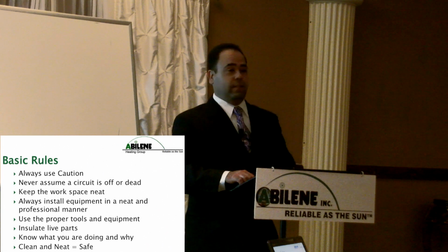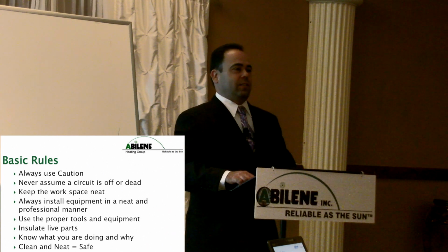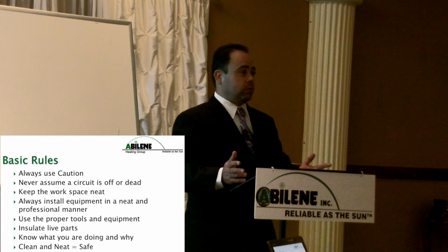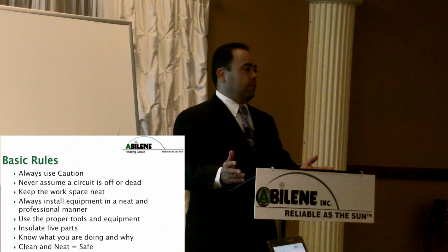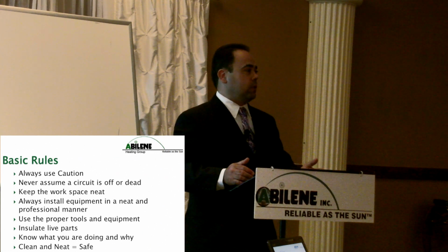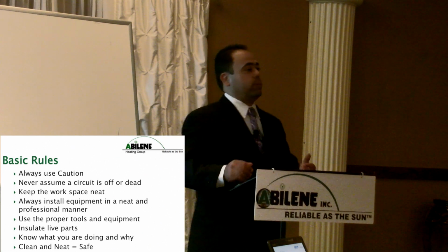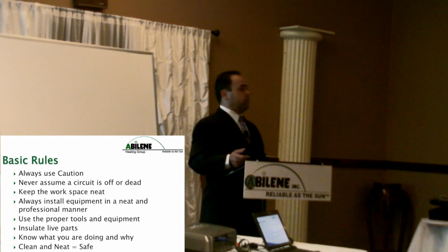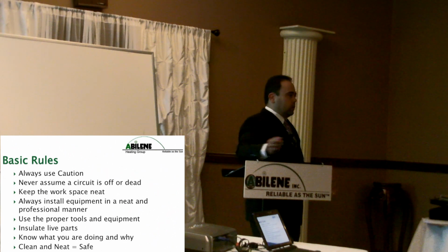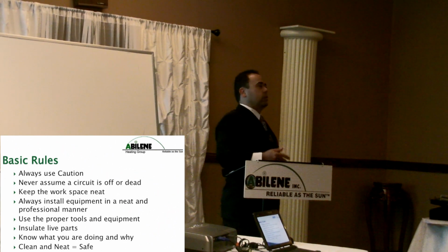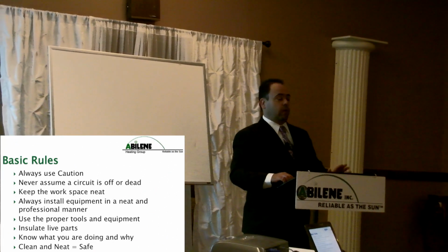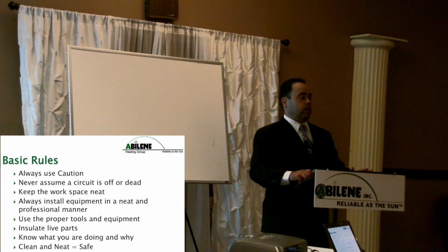Keep the workspace neat. I'm a stickler for this. All right? When you're working with open wiring, open panels, remember, we're with open panels all the time when we're working in a boiler room, right? Those are open, live buses. If you keep the area neat, there's less chance of somebody tripping and falling into the panel, getting hurt. There's less chance of pipe being everywhere, wire hanging all over the place, a short circuit, something hits that. All right, neat is always safer. Everyone will always tell you that. Nobody can ever deny that, okay?